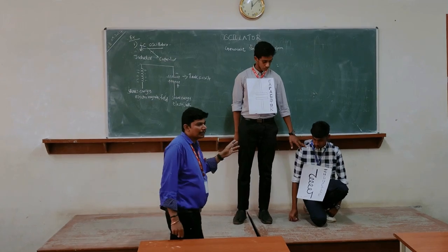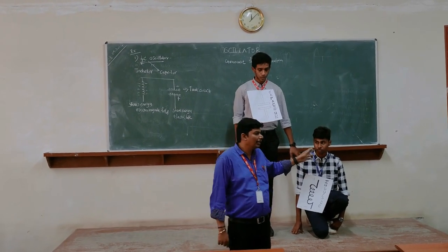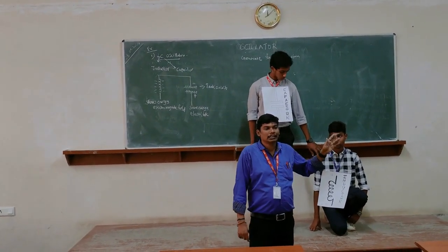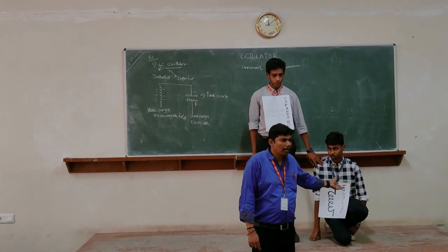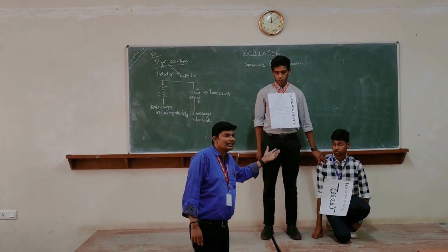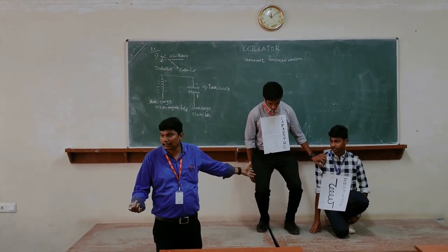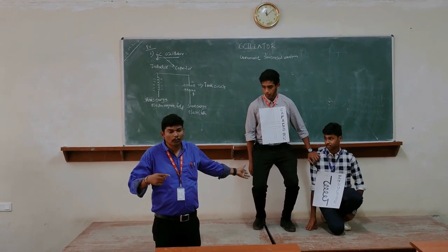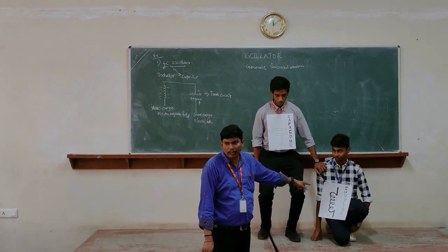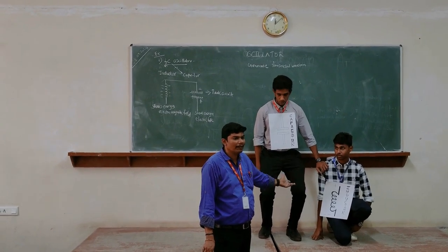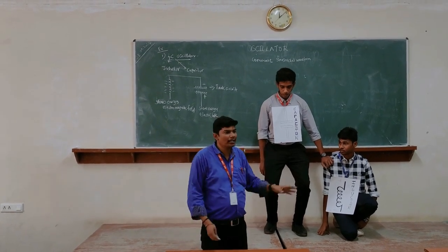See here, now the capacitor has full energy. But the inductor doesn't have energy, because it can only act upon when it has energy. So now the capacitor is going to discharge, because there is no supply connected here. There is no closed path for the capacitor; there is only one closed path, which is the inductor. So whatever happens, it has to discharge all the charges with the help of the inductor only.